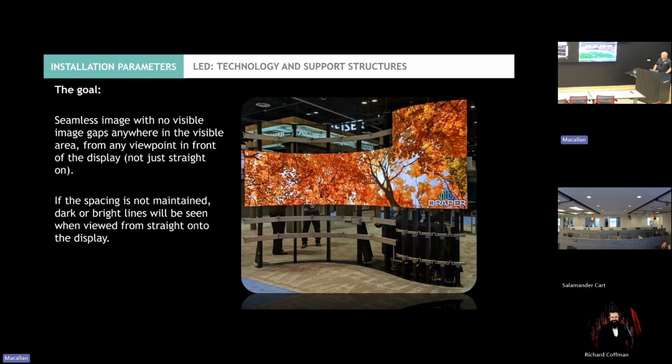And the trickiest part is there is a very slight expansion to LED walls as they heat up. So you also have to take that into consideration for the flatness overall. You are doing a tight fit, but the LEDs, once they heat up, will have a very small amount of expansion. Over a big wall, that can be a tougher tie-in.